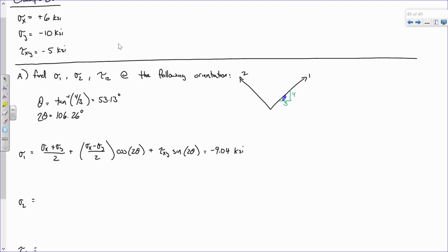So shear is usually, I mean, you need to maintain your sign for appropriate transformation, but from a mechanics perspective, if there's any one stress where the sign matters the least, it's shear. I'm not saying it doesn't matter. I'm just saying it usually matters the least. So, everybody okay? All right, so here's sigma 2. The formula is very simple. So if you can go into your calculator and just change the signs from your previous calculation.